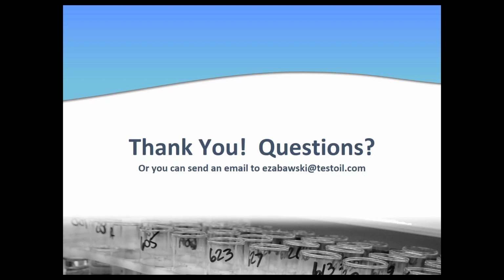I say might because, again, they're measuring it from a different way, so the way we would get those results are a little bit different. Ruler does require a new oil reference, and it's always comparing back to that, whereas infrared does not require a new oil reference and is just a direct measurement. Now, the overall trend of those two results should be in the same direction, in that they would both decrease accordingly. But no, ruler won't correlate, as I said, with any of the other degradation or basic chemical property tests like acid number, viscosity, RPVOT, ultracentrifuge, or MPC.